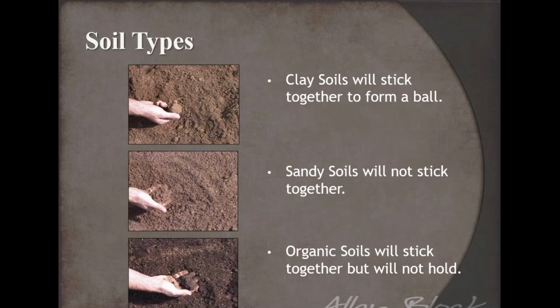We know that if we grab that sample of soil and we can ball it up, we probably do have that cohesive soil, as we've talked about before. But if I take that sample of soil and try to squeeze and it doesn't really stick together, you're probably looking more at a granular material. And that can actually be advantageous when we're talking about retaining walls.